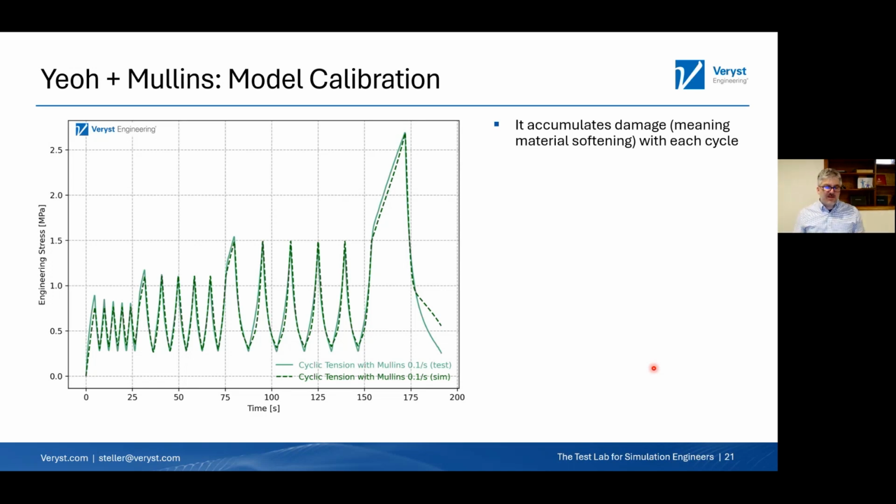To take a step back, you can get a pressure dependence between those different loading modes, and that's why they recommend that. And there are some models that can capture that. What I have found in my experience is that that pressure effect is generally very low compared to time effects, temperature effects, things like that. The test modes to get that data are generally much more difficult and have a higher uncertainty on them, and it's generally a small effect. So my philosophy is normally that it is going to take a lot of extra effort, and we're going to improve the model by a very small amount. So I think uniaxial tension or uniaxial compression will be plenty.